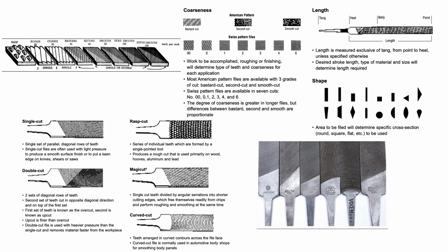Because of the double teeth, this file cuts metal quickly, but it cannot make the surface very smooth. So that is why it is generally used for normal filing. It is also called a coarse type file, with angles of 30 degree to 35 degree, and another row at 80 to 87 degrees.